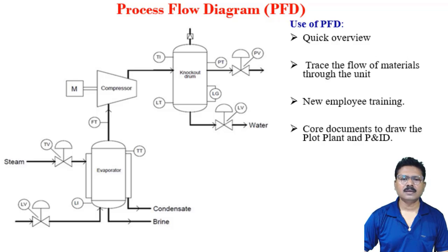To show a practical process example with process flow diagram, let's examine three diagrams here for a compressor control system. In this fictitious process, water is being evaporated from a process solution under partial vacuum. The compressor transports the vapor to a knockout drum where some of it is condensed into liquid form.